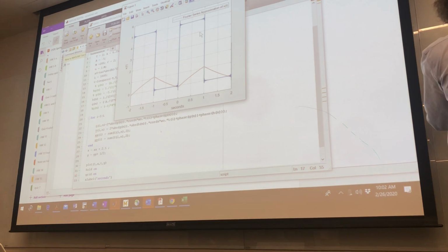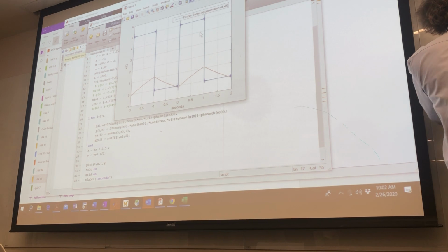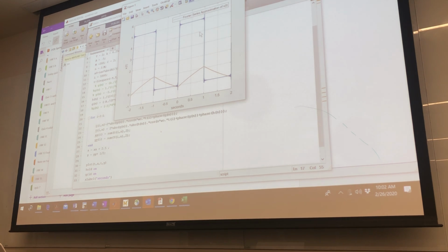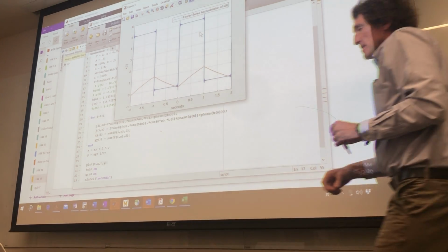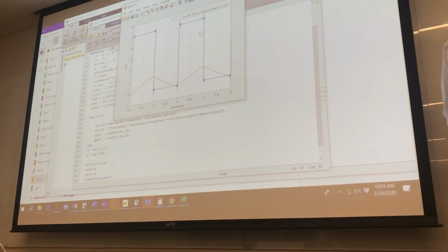In the problem, it states that I have a current source here, some I of t, and then I have, I believe, a resistor here of 1 ohm. You tell me if that's right or wrong. And then I have 1 ohm over here, and I have an inductor here with a value L equals 2. The resistor at the top won't matter anyway, because you have a stiff current source.